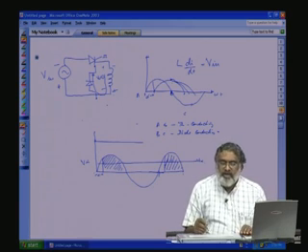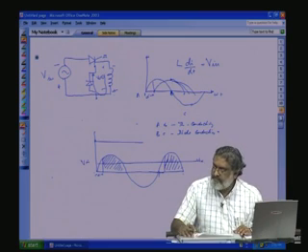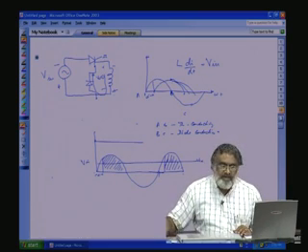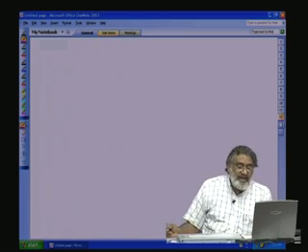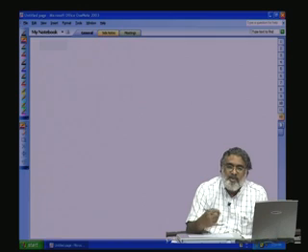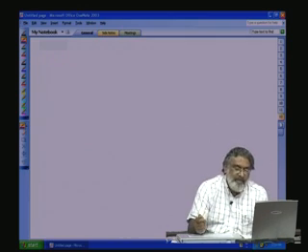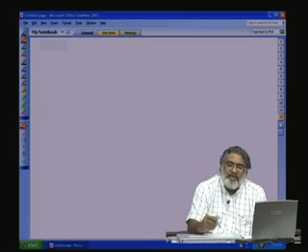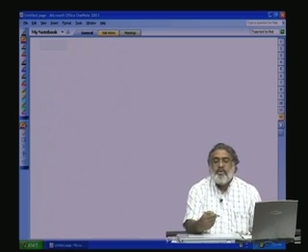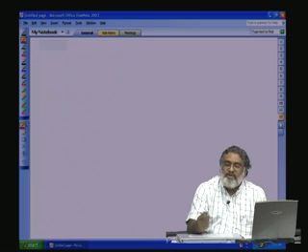Now, let us not stay with the half bridge concept, let us go to the full wave converter. Let us go to the next page. Full wave converter will give higher DC voltage. That means we are using the input positive side as well as the negative side to transfer energy with reduced ripple. So, this is basically rectification, whether half bridge or full bridge. The input AC is rectified and brought to the output. It has DC as well as the ripple content, that is high frequency component.